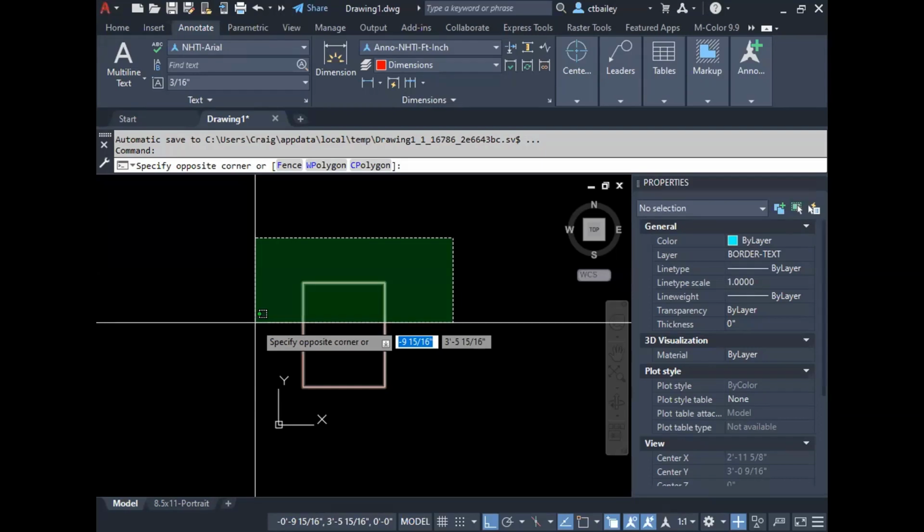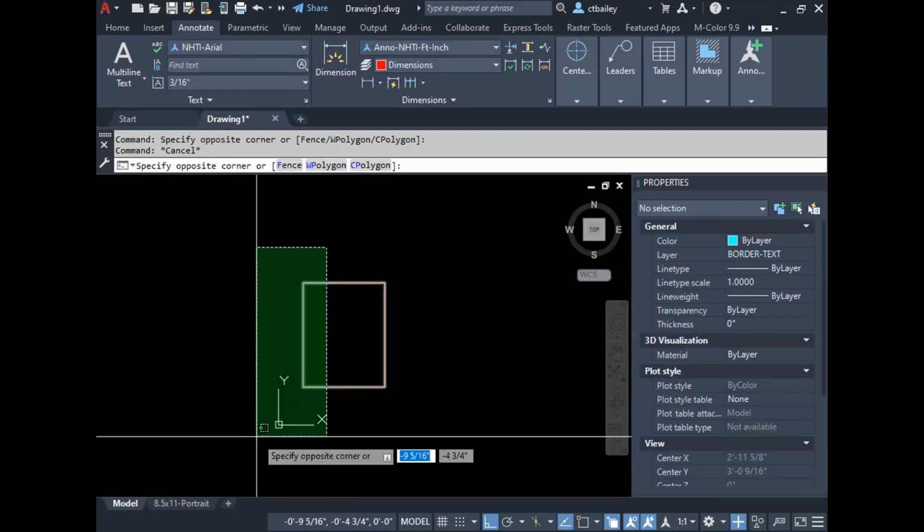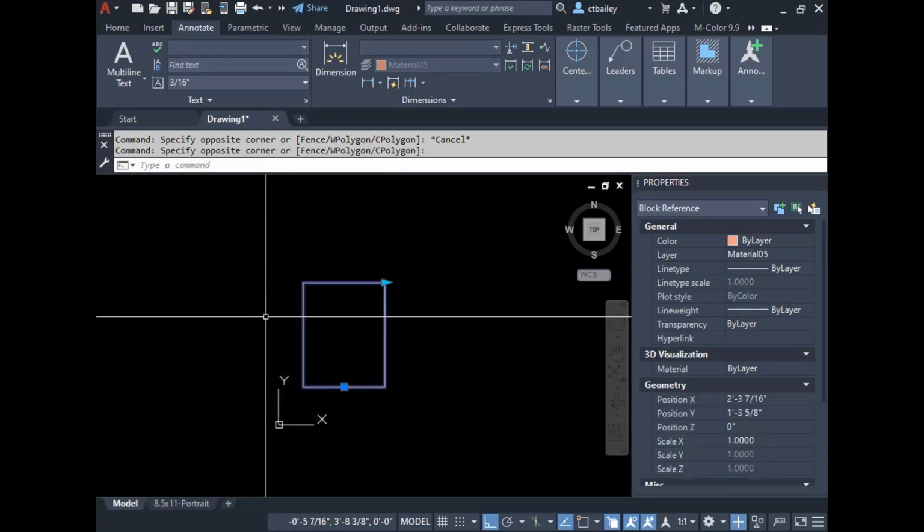Your vertical selection frame is right there. So when you grab your grip edit and translate vertically, you're going to move that segment, and these two guys here have to stretch. Not all the correct parts of the shape are selected. I want to get this thing to stretch this way, which means leave this one perfect and stretch these two. So what should the crossing look like? Your crossing right now happens to be just this side.